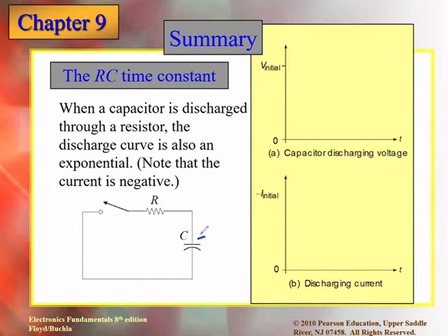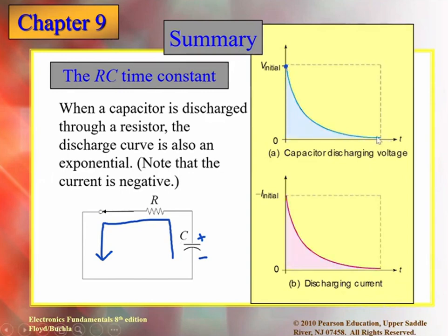And how is it there? Initially, now can you tell me what will be the initial value of the charge across the capacitor? Will it be large or will it be small? Large, right? So it should be V initial. That means the initial voltage across the capacitor will be larger. And what will happen, girls, as I close this switch? It starts giving back the energy to the circuit, to the resistance already connected. So current will flow in the reverse direction, and it will start giving the energy to the circuit. Let's see now. From the start value, it is now going to be reduced to 0.